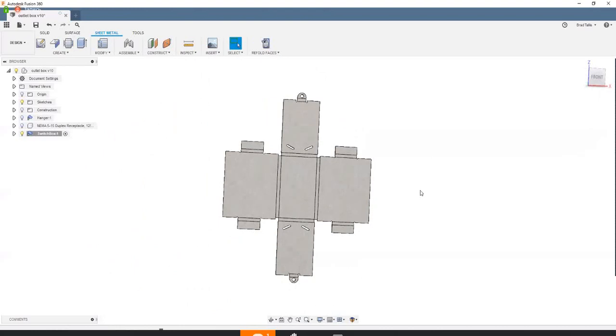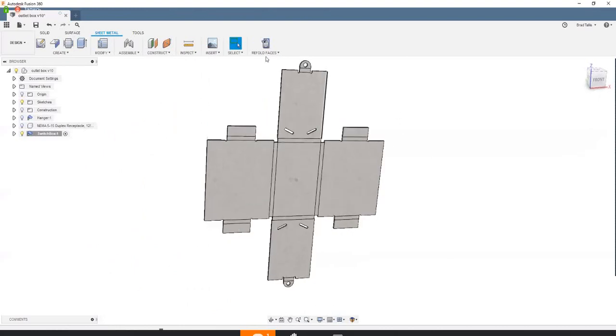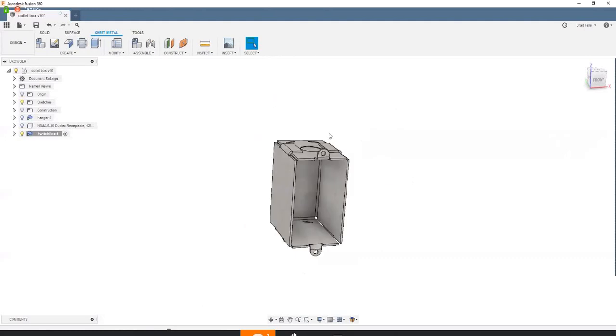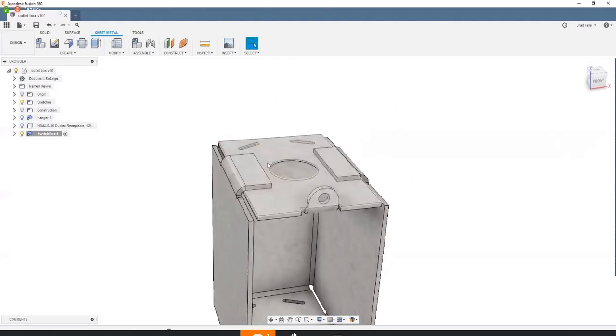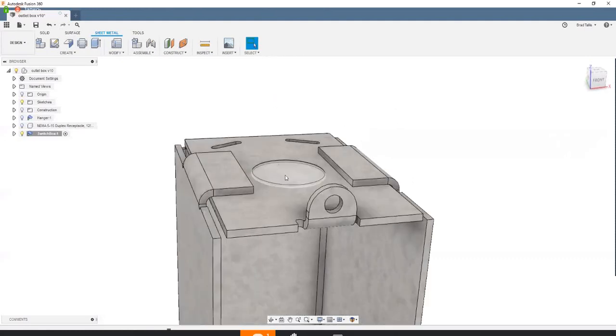And again, it kind of depends on how this is going to be manufactured. So, for example, this is going to be basically stamped in there. If I wanted to create a dimple, I would just create a revolve, but that's actually physically deforming the sheet metal. So, maybe you just mark a location and say use a standard 0.5 dimple tool or something like that. Again, it's really up to you how it's going to get manufactured.